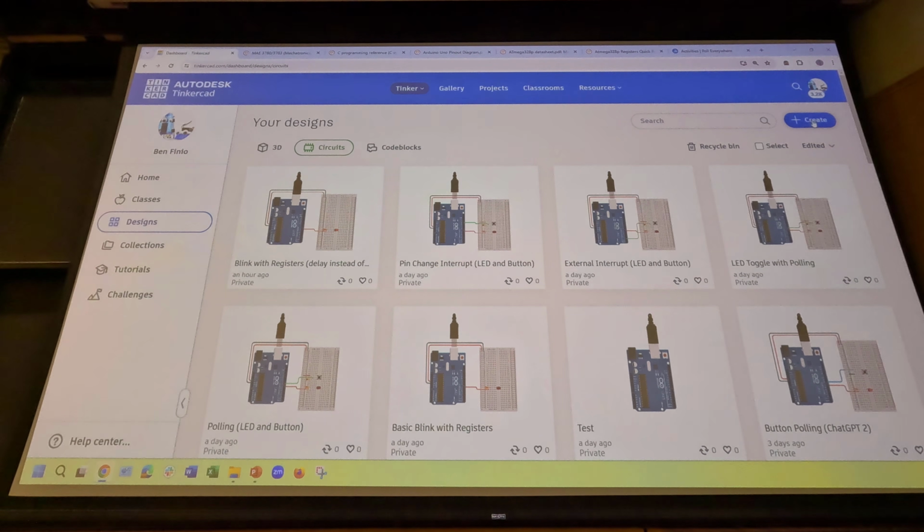So we're using LEDs for these circuits because the wiring is simpler than the H-bridge, but the code is the same. Okay, when you want to steer your robot, you are going to be setting digital pins high or low, and that's going to correspond to whether your robot is going forward, backward, turning left, or turning right.